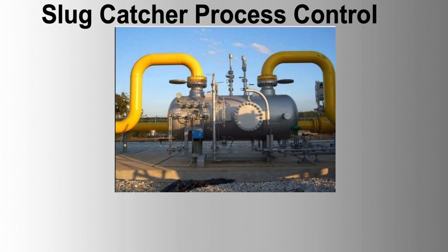2. Gas pressure feed-forward control, FFPIC, feed-forward pressure indication control. Objective: preemptively manage gas pressure within the slug catcher based on upstream pressure changes. Mechanism: measure upstream pressures and anticipate their impact on the slug catcher. Adjust the gas outlet control valves and pressure relief systems accordingly.